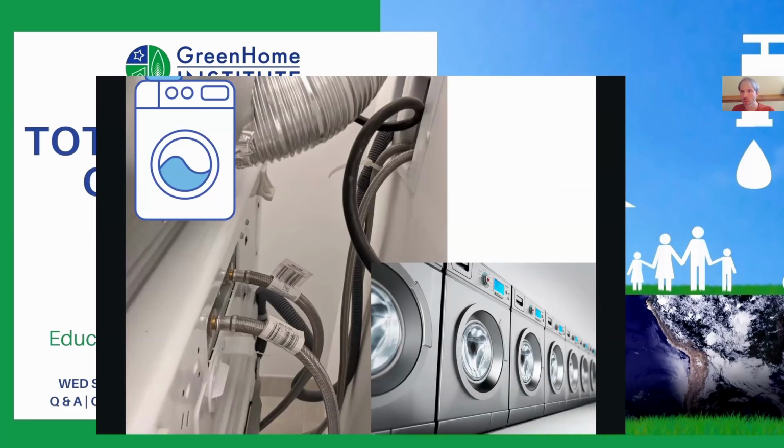So as with everything, when it comes to green building and LEED, it's all interconnected. We call it the 5 pillars of green building. There's always these inherent things that tie together. So this is an opportune time to think about the requirements for clothes washers that stretch into durability and into the materials and resource section, as they call it in LEED. Because if the developer is not supplying their own clothes washers, then they either have to pre-install expensive drain pans or pre-install steel braided hoses, which reduce leakage compared to rubber hoses by 90%.